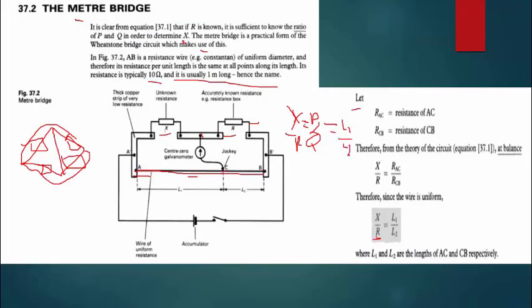These lengths mean resistance. If you remember, resistivity is equal to resistance times area over length. So automatically, speaking of the length, you speak of resistance. Because the diameter you know, you can measure and calculate, and resistivity is a constant value. And length is like that, so automatically these are like resistors. Okay? Because it is the same wire, that is why they cancel here.